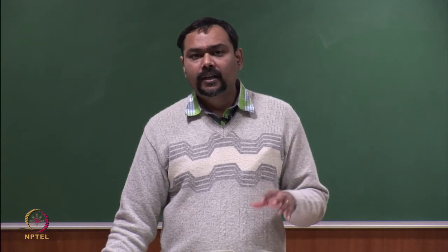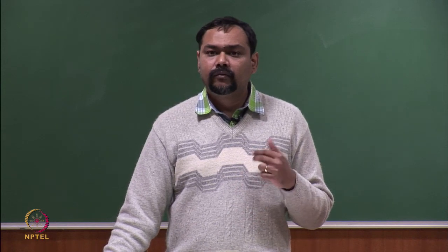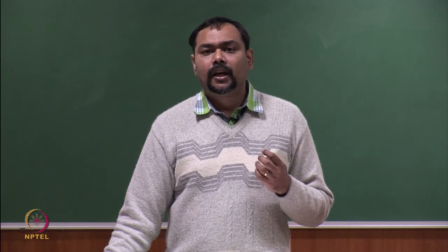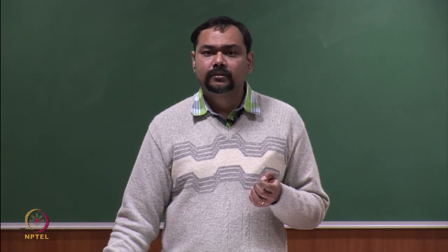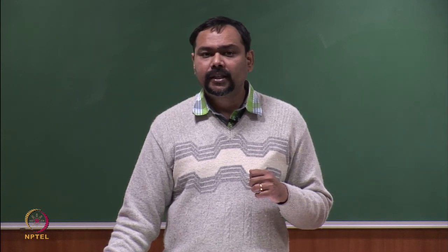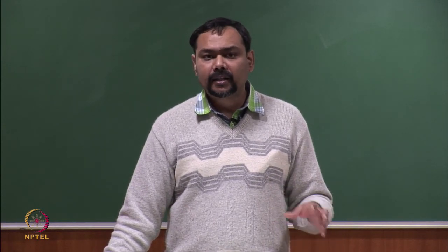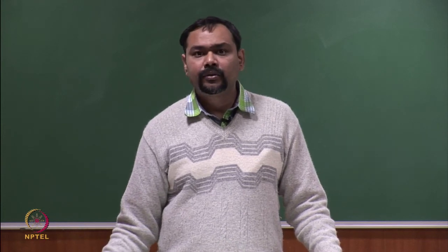We started with the basic topology of NPC, then we talked about the space vector diagram, and then we also talked about carrier based PWM implementation. We also talked about capacitor balancing, and we briefly touched upon some other topologies of NPC which you can explore further.